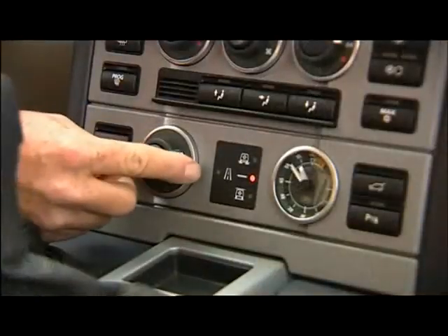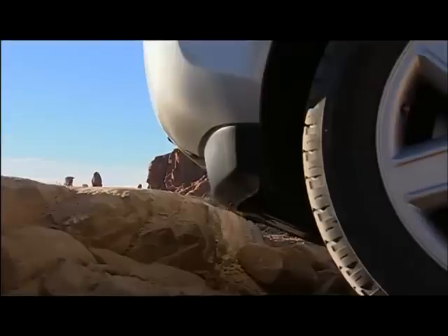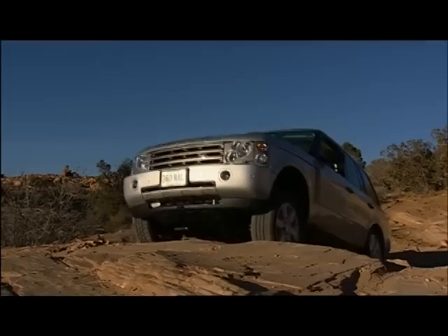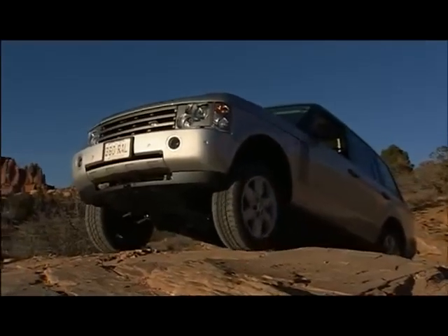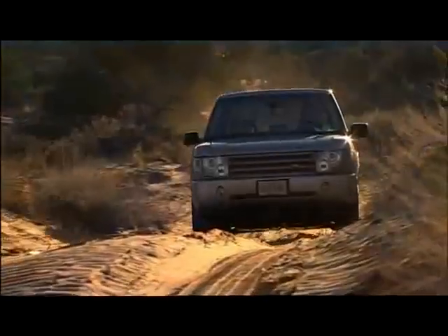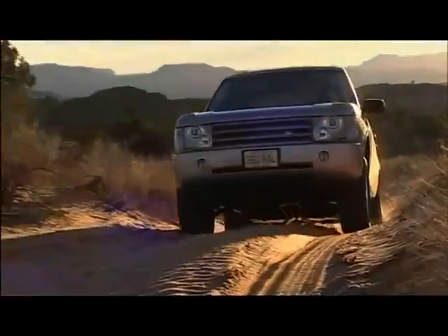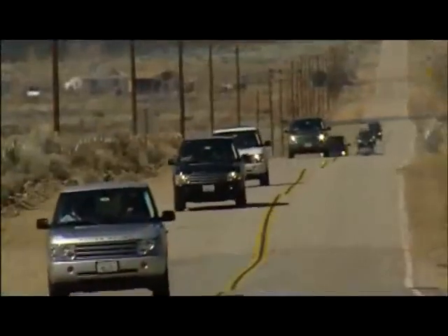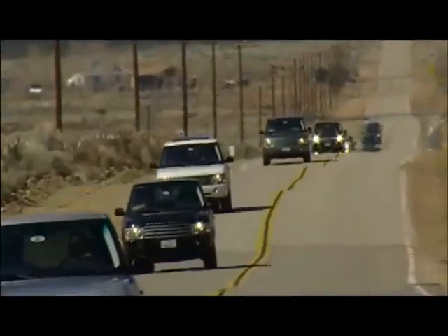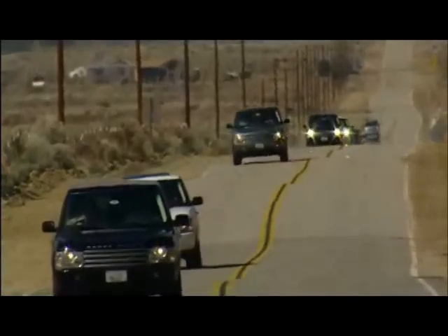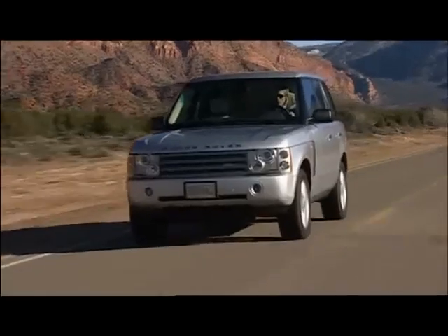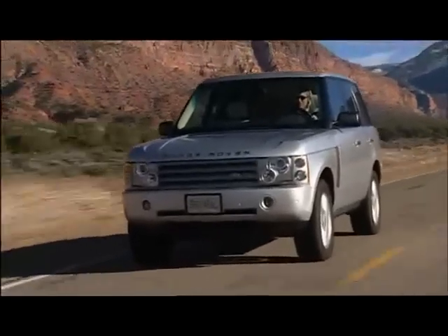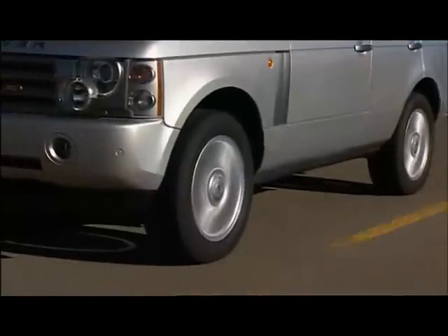To increase ground clearance for off-roading, you can raise the entire vehicle 2 inches above standard height to off-road mode. When changing heights, all doors must be closed. Off-road height will be maintained until vehicle speed exceeds 30 miles per hour. In addition to the 3 selectable heights, there is a 4th position called highway mode, which is not selectable. At speeds over 60 miles per hour, EAS automatically lowers the vehicle slightly less than an inch below standard height.